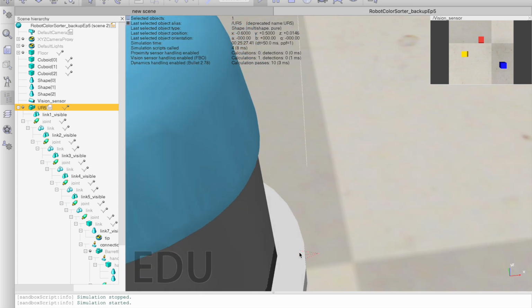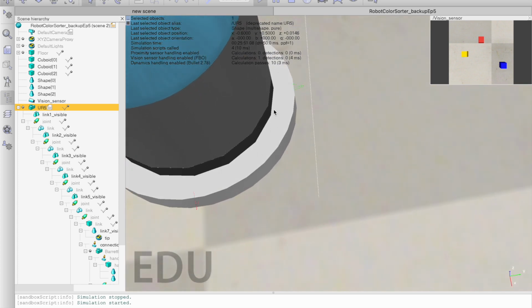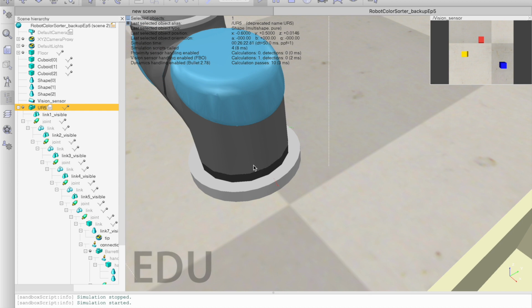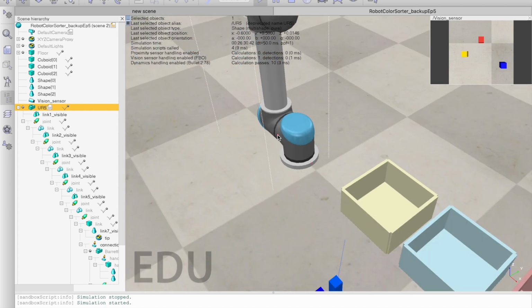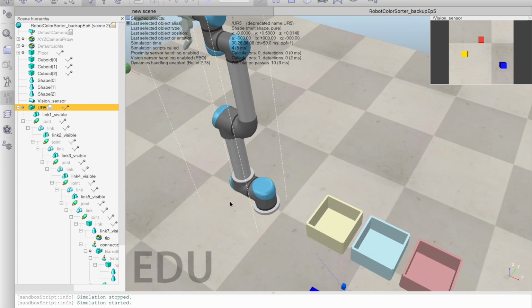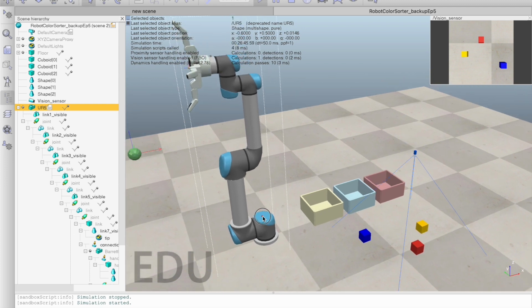That means the X direction is also in this direction, positive, same as the main reference frame. And so is the Y. So the Y is in that direction as the global reference frame, which means we can conclude that the Z is also upwards. So now we have the position of the camera with respect to the robot.